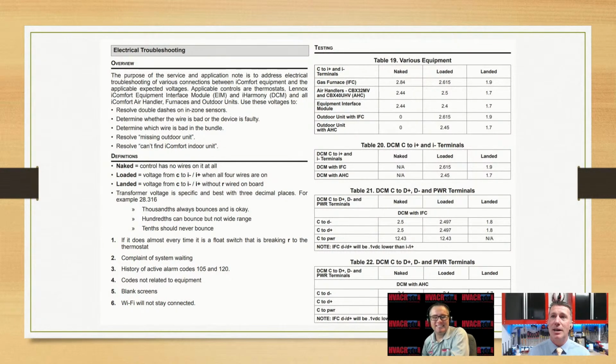I run a fresh conductor and then retry it, because you will have nuisance issues with communicating wires on existing thermostat wires that didn't have any problems when you were running a contactor. With a contactor, my current was going through the conductor, utilizing the entire circumference of my conductor to get my current through to create a load on my contactor. With communication, a lot of times I'm running around the surface of it. I'm not putting a lot of current through it, so it's communicating.